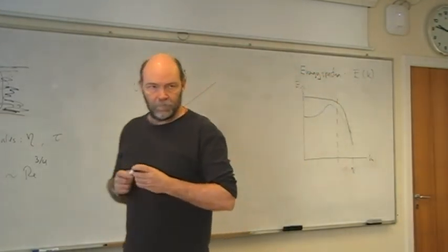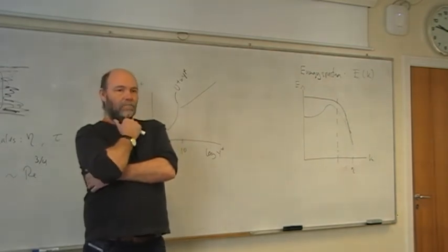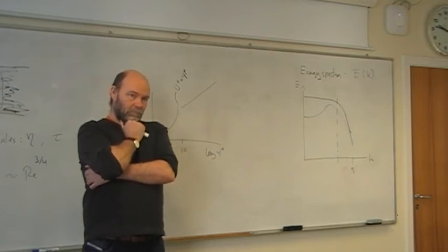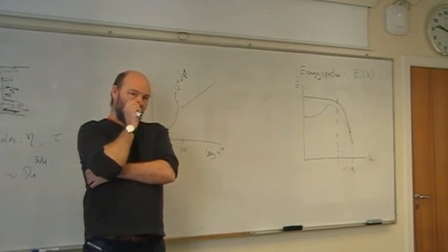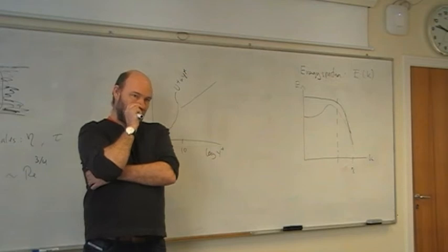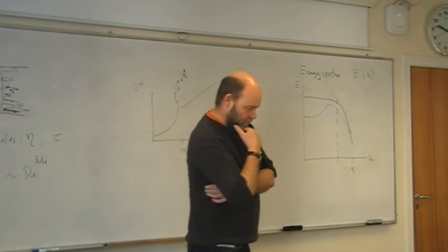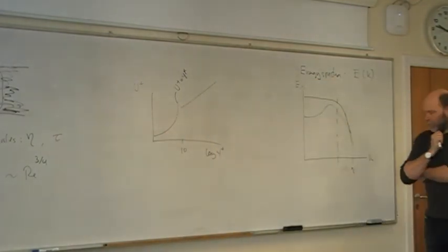I've heard that it actually can be dangerous to just trust the energy spectra, so that in some cases you would actually get a spectra which looks quite nice, but you still have too poor resolution, and that you rather should look at the 2-point correlation and then see, okay, how many cells are in between. I would say, I would still put a question mark.